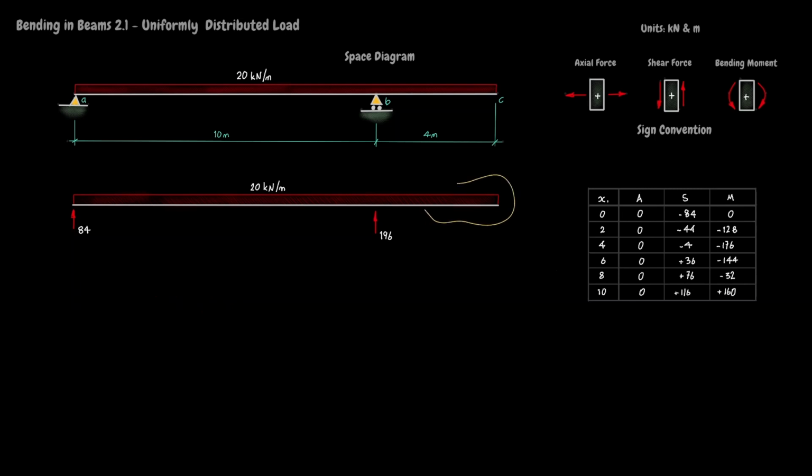Notice that Dr. Jim has chosen a free body diagram bubble that isolates the beam to the right of the cut. This produces a simpler free body than the alternative. Using a free body diagram bubble that isolates the beam to the left of the cut will result in a free body that includes both reactions as well as the UDL.